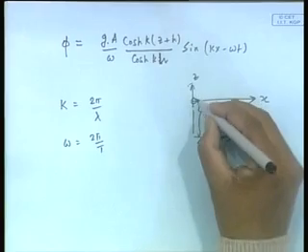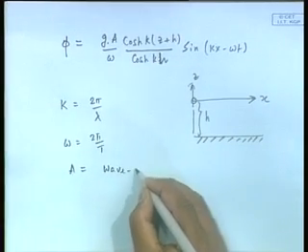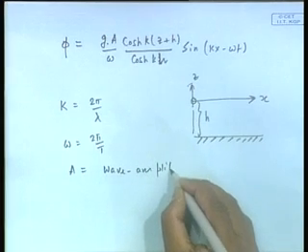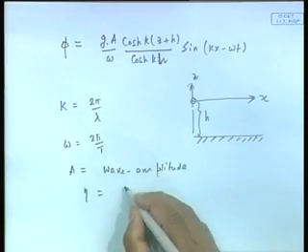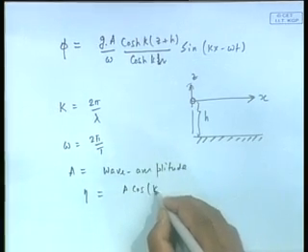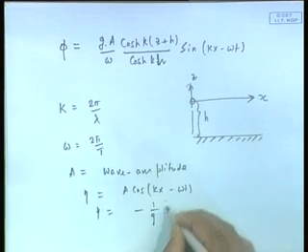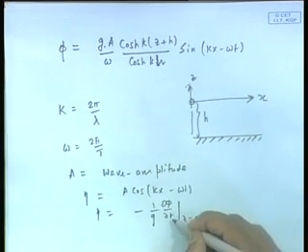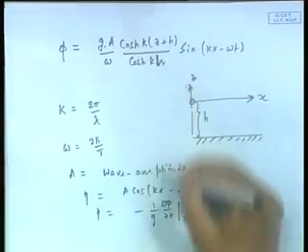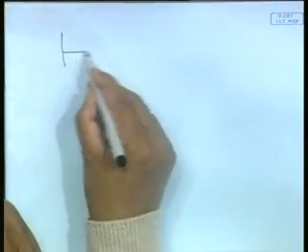The wave here is having an amplitude a, and the wave profile eta is given by a cos(kx minus omega t). Actually this eta is obtained from the fact that it is minus 1 by g d phi by dt at z equal to 0. You can confirm that if I do this operation on this, it becomes like this. So, here the wave profile would look like a cos curve.